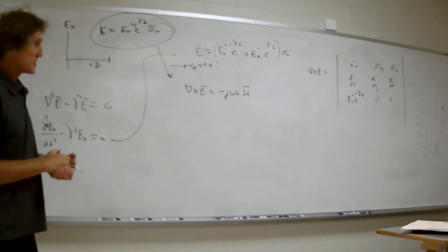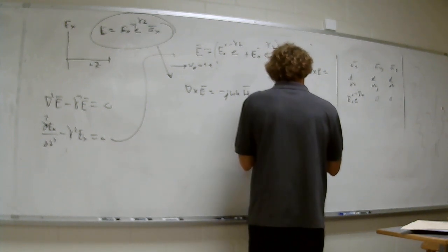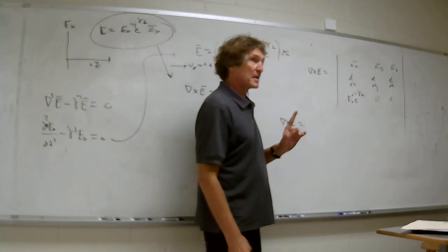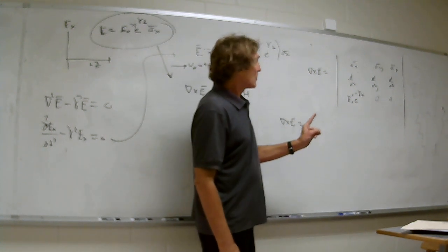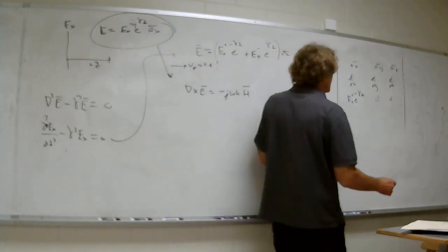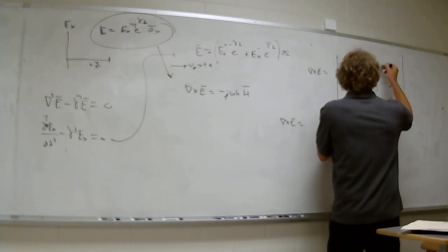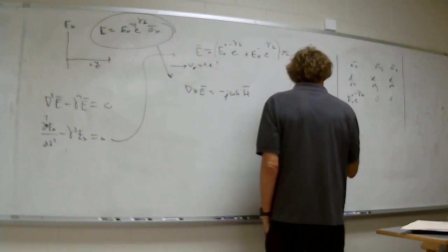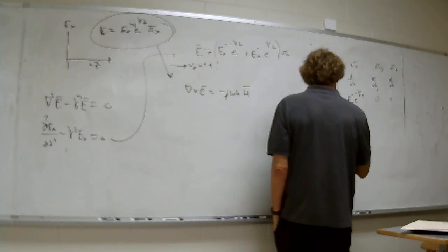All right. So, what is the curl of E going to be? Well, take a look. Remember, I specified the E field is polarized in the x direction, and it's propagating in z, right? When you do that, what happens? Here you're going to get a_y times d/dz of E naught e to the minus gamma z.